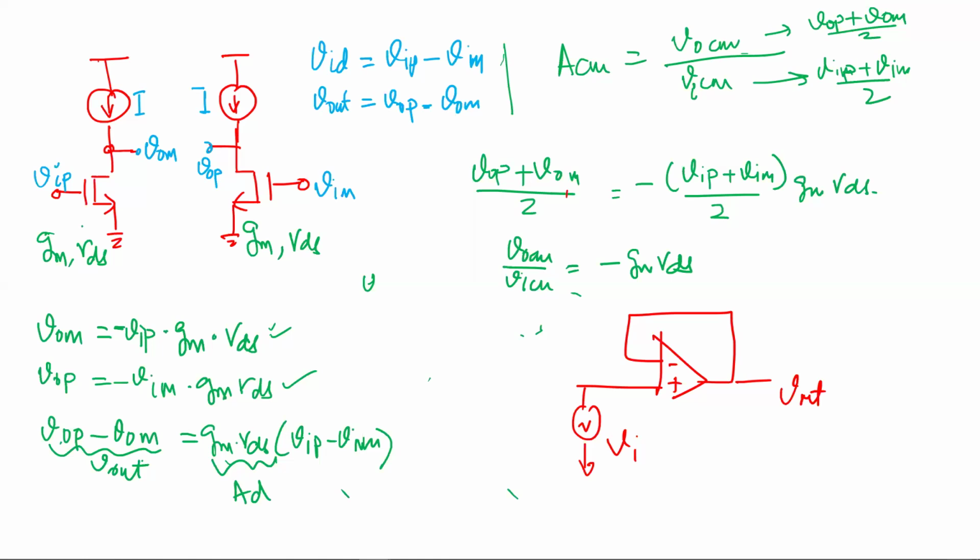So obviously I didn't invent this, but the popular one is you basically take that same circuit you had before, and we'll change that R later on, but let's first find out. Now what we're going to do is give the bias current from the source itself. So if we do this, then when the voltages are the same, and let's say the sizes are exactly the same, this current has to go half here, half here. Correct?